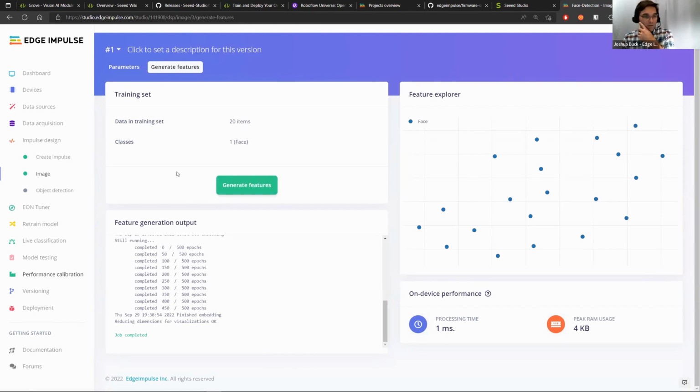For here, this particular block is taking what might be a full-size high-resolution camera image and shrinking it down to, I think Lakshantha chose the 96 by 96 feature output, right? Yeah, 64. Oh, 64, sorry. Right. The 64 by 64 image is what will be fed to the learning block essentially to train against. And when you eventually run on the device, the camera is taking a full resolution image, the processing portion of the code will shrink it down and then feed it to the model. That's to give faster inferencing and not to make the model blow up to be a couple megabytes. You don't need every single little pixel in order to do face detection, for example.